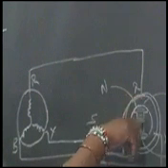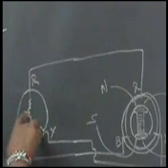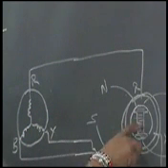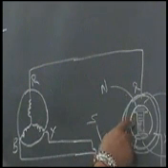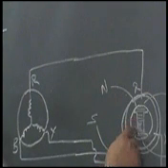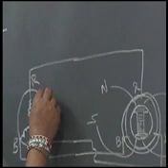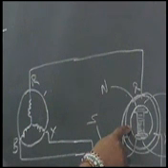So this magnetic field will be rotating at such an RPM that it is equal to the RPM of the magnetic field there. So the synchronous speed means the RPM at which the magnetic field at the source is rotating, provided we make the number of poles the same as here, 120 F by P.